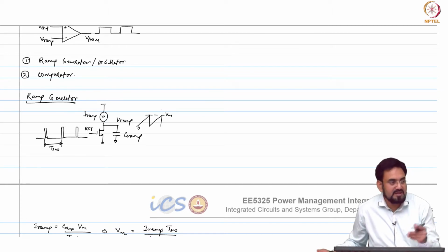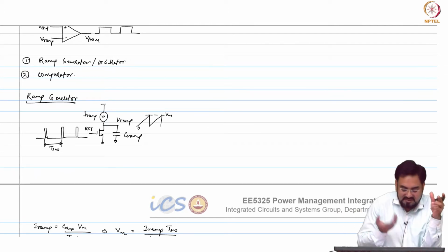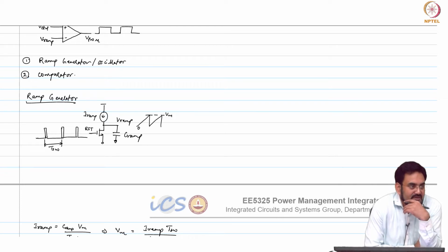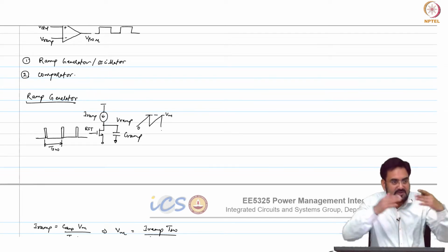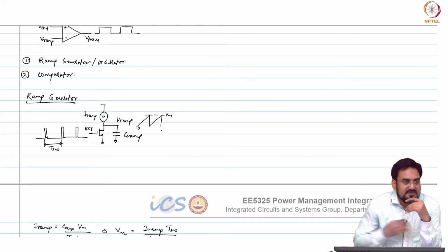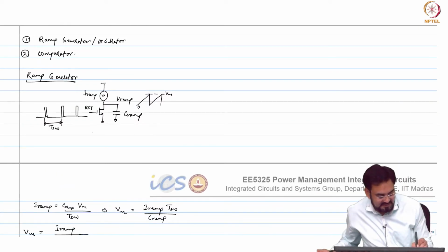If I am talking about 1 megahertz or so, which is 1000 nanosecond, then usually we keep this reset time order of 1 nanosecond, so that it should not affect your PWM, because we are looking at single edge. If you make this slower, then it will look like a dual edge modulation, then your behavior will change in that case. So this is your leading edge, trailing edge.